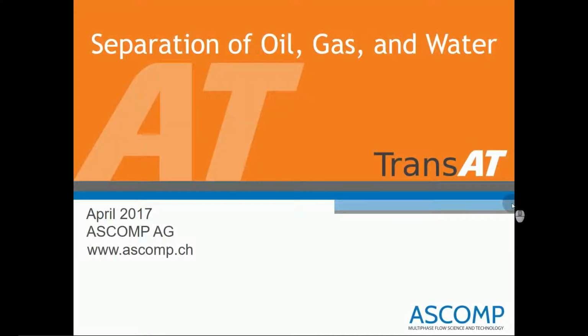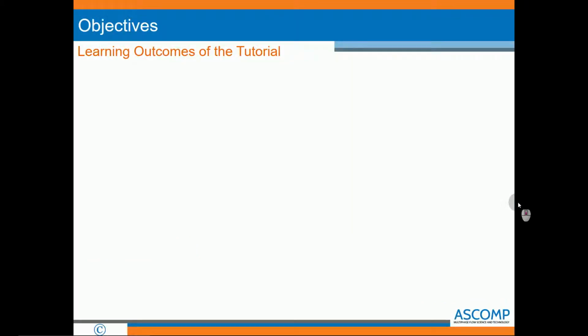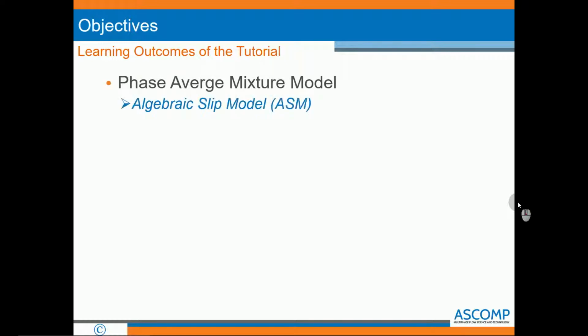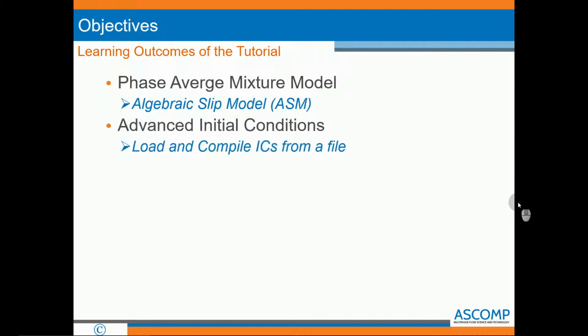In this video, I will be demonstrating the oil separation tutorial in TransAT. We will be looking at a separation of oil, gas, and water. Through this tutorial, we will use the phase average mixture model with the algebraic slip model, and we'll use advanced initial conditions. So you will learn how to load and compile initial conditions from a file.